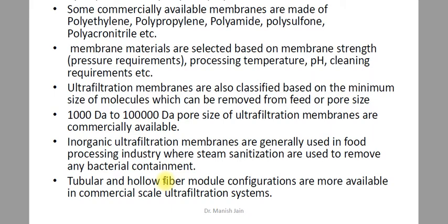So it is opposite. It is not that the feed flows in the tube side and product flows in the shell side. In ultrafiltration membrane, always the feed flows in the shell side, so that the microparticles cannot start to clog the pores of the membrane. Okay, the tubes of the membrane. So always in the shell side you have the feed flow, and in the tube side you have the product flow.